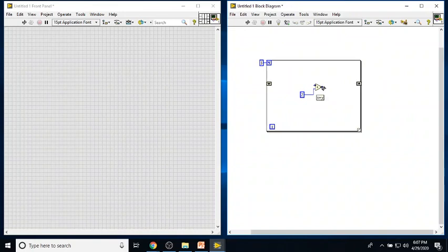So what I'm going to do is, from here when I connect it, you will see that the shift register has converted its data type. I told you a shift register is nothing but a memory element. So it is now having a memory unit which is going to hold one item, one number of a numeric data type. Right, from here I can pass it like this. Fine. So this is a kind of feedback system where whatever I write on the right hand side shift register is now fed back here, and I just take it as an input. Output of my addition is coming as an input using a shift register.